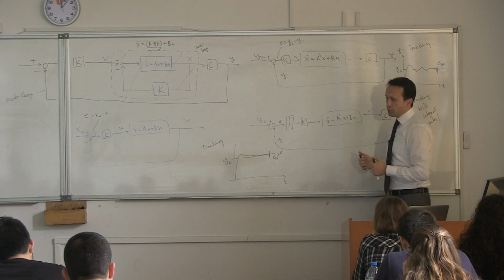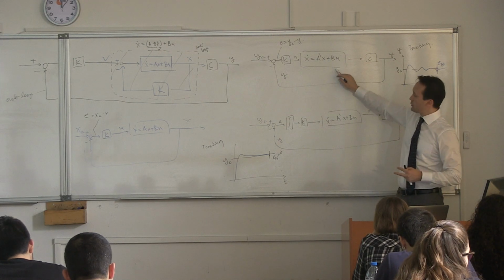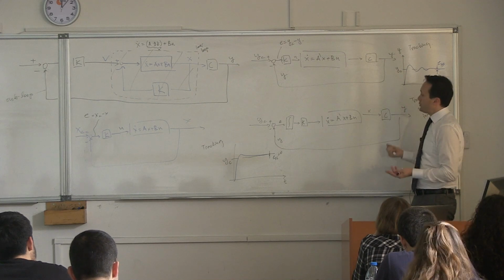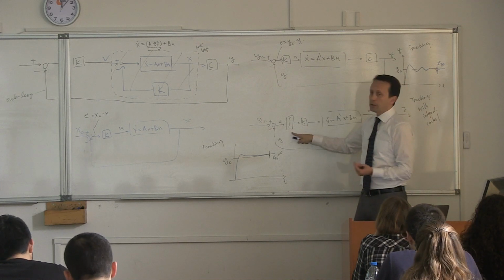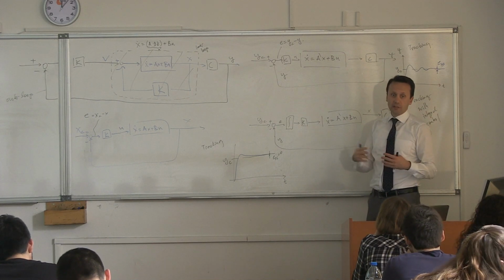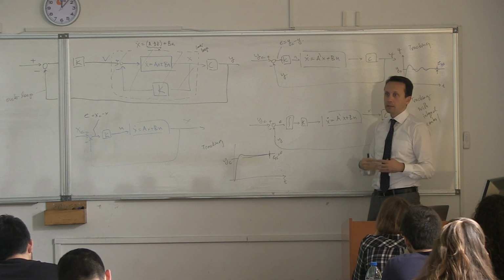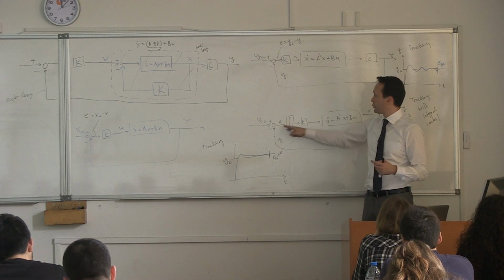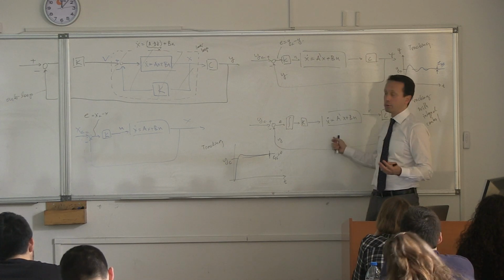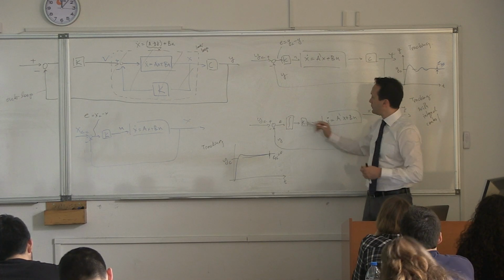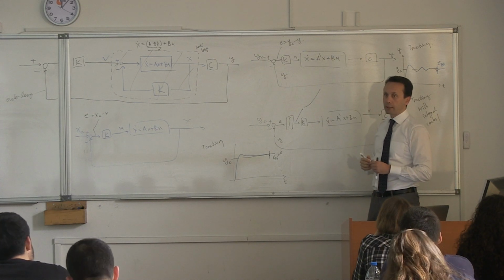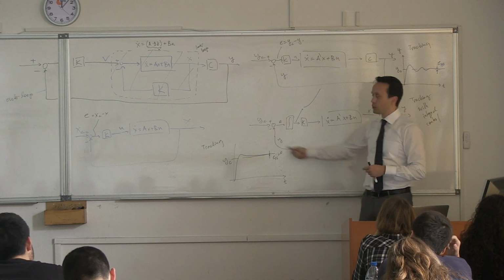So, of course, you might say, why would anybody use this when you can use the integral controller without the steady state error? Well, the reason is when you have an integral, you have to be careful. The integral has to start somewhere, right? It has an initial condition. And if the error keeps growing for some reason because of a measurement error or something, this number here, since you're integrating, might diverge very quickly if the measurement here is not correct.